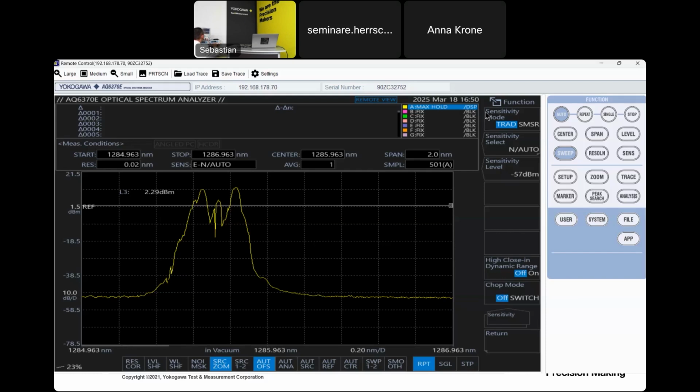Now look at the instrument. I don't know if you can see that the percentage of progress of the sweep is not changing equally. So we now have pulses with different pulse widths and different repetition frequencies, and this can also be handled easily in this mode.